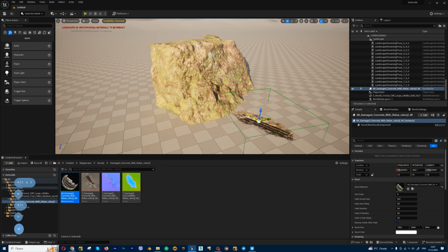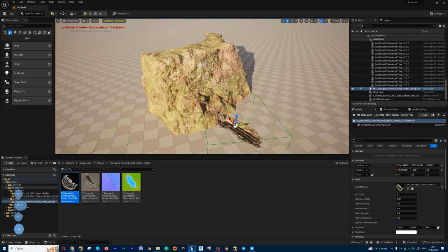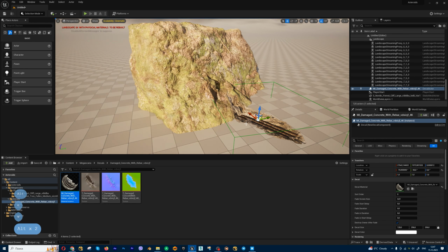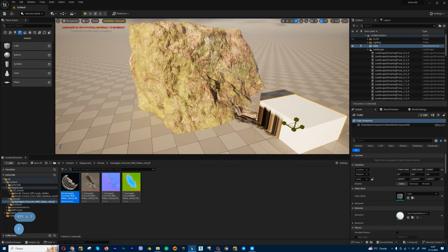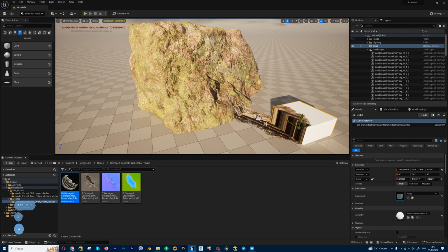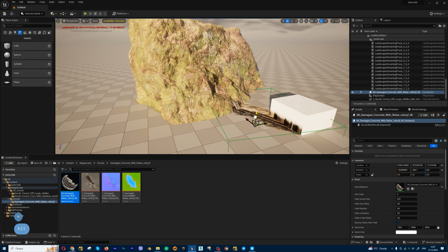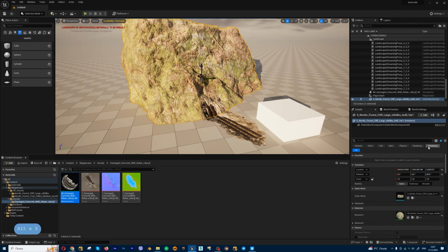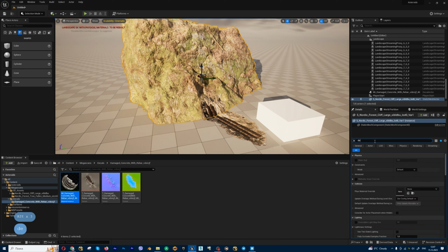A very interesting moment I'm going to show you. If you place your decal, you can find intersection with all objects. For example, let's create a cube. You can find this ugly stuff. So we have this green boundary zone, and you can move your green zone like this. Also, in all assets we have a receive decals checkbox.